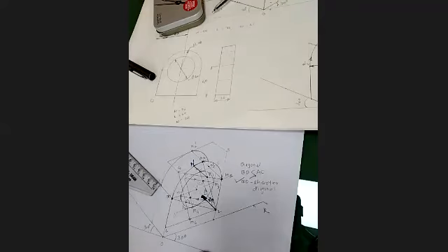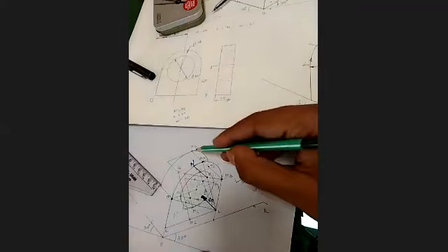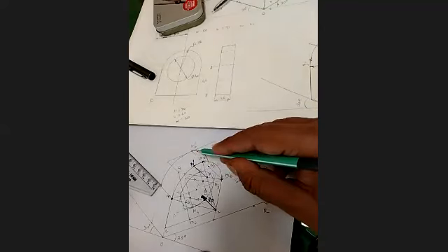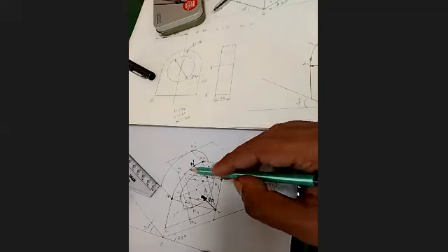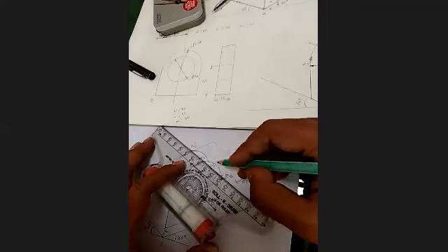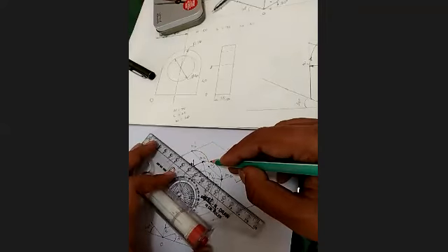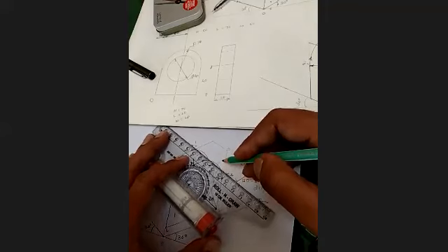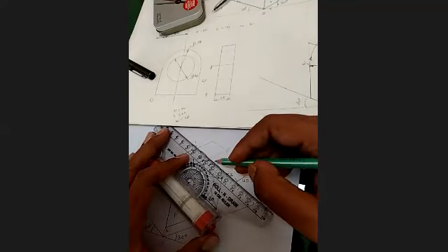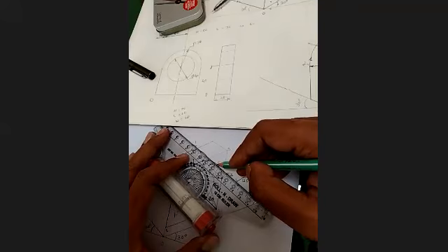Yes, sir. See, this arc and this arc zigzag, it is not possible. This kind of surface is not possible. It should be plane. So what we will do, we will draw a line tangent to this arc and this one. If you get the tangent, you will realize how it gives the perfect view. Draw a line tangent to this.